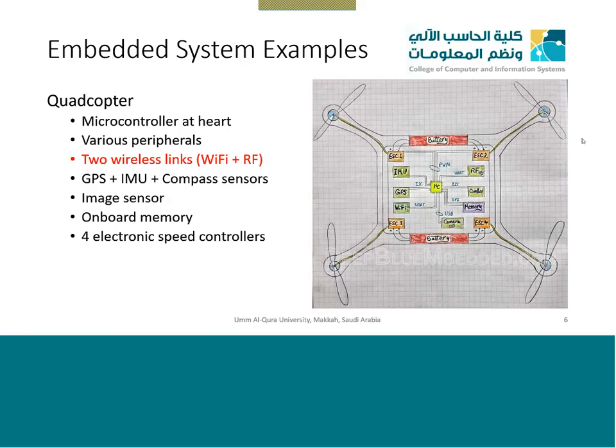So if you are a person designing this, you just need a processor. You will connect it with 4 motors. The speed of the motors will be connected to the RF. It will take the input from the remote control, and based on that perform the operation to send some data to the 4 electronic speed controllers, ESC 1, 2, 3, 4, which are connected to the fans to move them left or right. Everything will be done in the code. The hardware is very simple. You will just connect 2-3 wires to all these things, and that is done. The rest is on the software side in C or Java, whatever language is preferred.